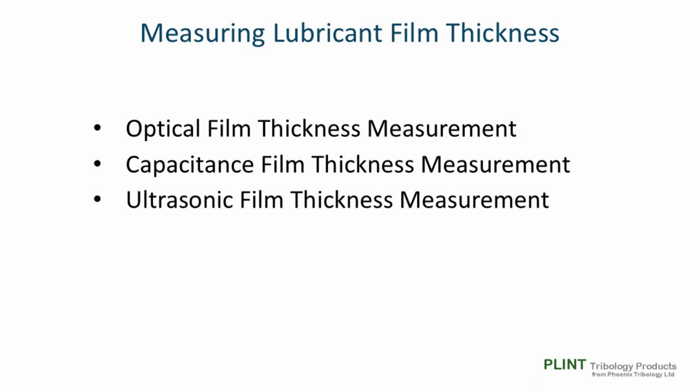There is a significant caveat arising from this. It takes something of an act of faith to assume that the lubricant tested in an optical elastohydrodynamic film thickness measuring device at 0.5 GPa is going to behave in the same way as at a contact pressure of, say, 2.5 gigapascals in a contact between a bearing steel ball and a bearing steel race. There is not much we can do about this problem.